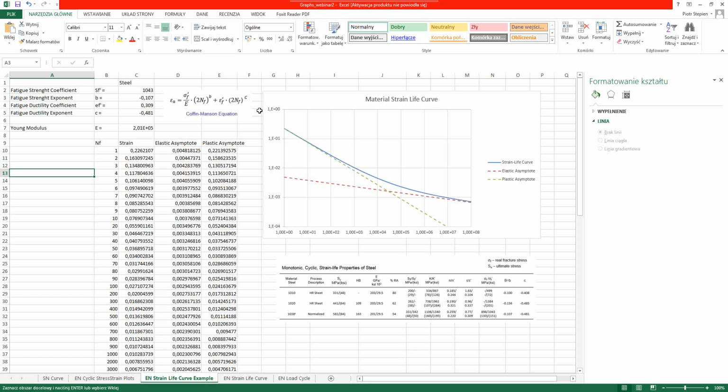Okay, as I said before, in order to calculate plastic strains, we will use Neuber's rule. I'm talking about this because now we have a curve, but we can use, let's say, the nonlinear response of our model using nonlinear static analysis, and we can create our curve as well. But today we are using this data.